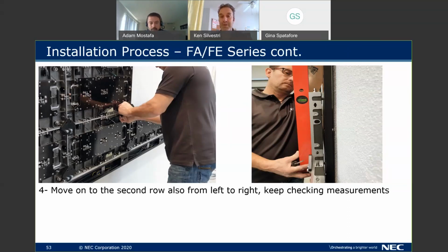You go back and tighten those considerably with enough force, and then come back and remove that plate. Now your modules are in alignment much, much closer than ever could be done before. And behind every single pixel card, there are additional 4 screws that are able to do minor Z-axis adjustments as you need. On the right, the technician is using a plumb on the wall, making sure it's level. The wall plumb can be adjusted from the front side very easily.